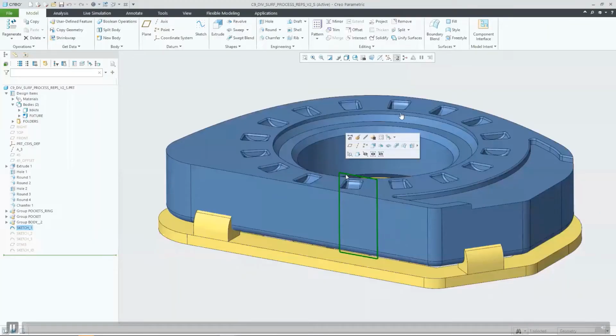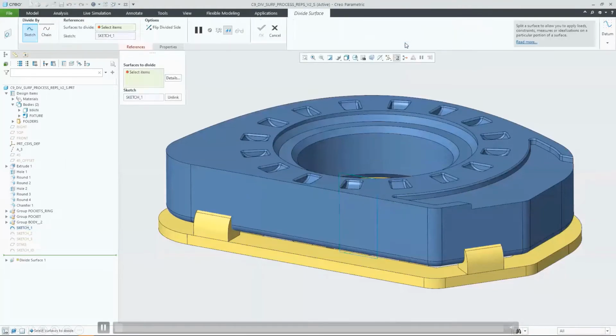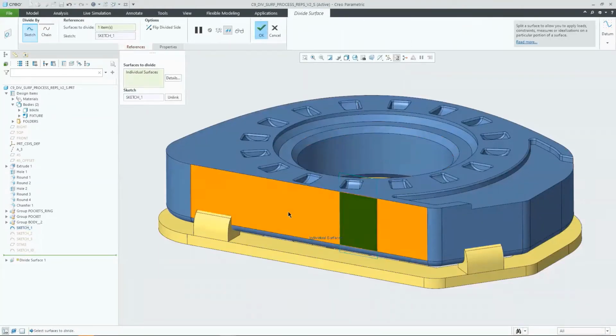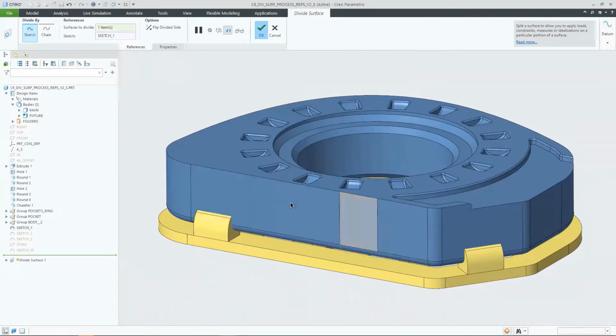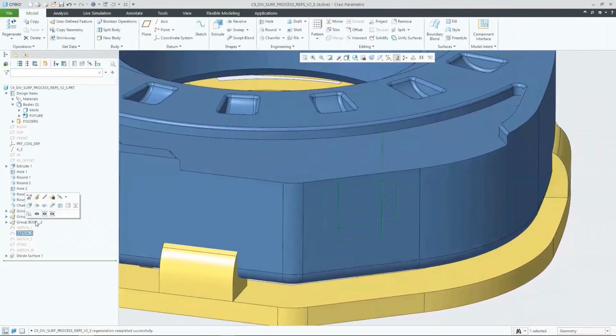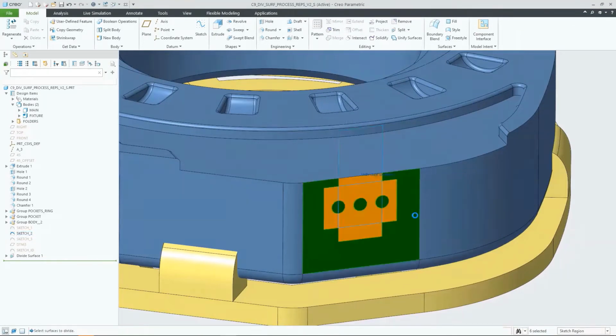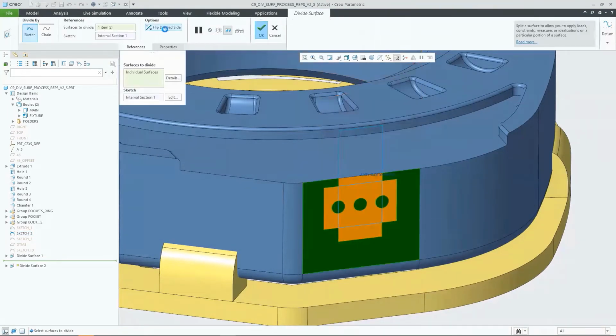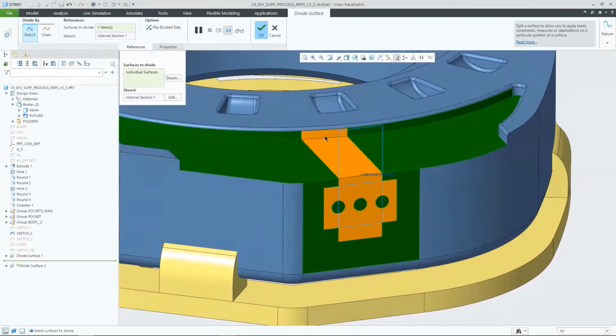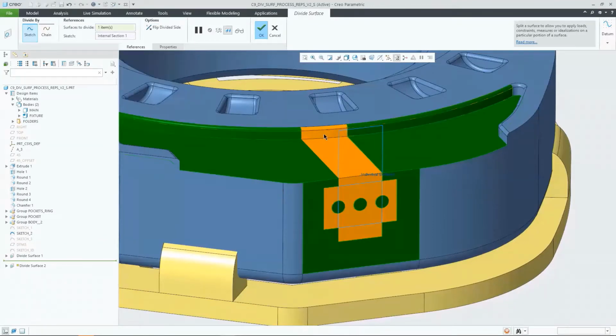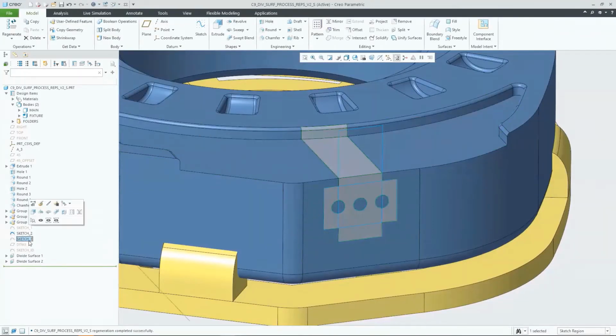Creo Parametric 9.0 introduces the new divide surface feature. You can now use the capabilities of the new divide surface feature in core modeling and throughout the broader Creo environment to split a surface area into a new adjacent touching surface that is based on the same surface definition as the original surface. This helps to better support a broad variety of use cases, for example in the areas of model-based definition, visualization, simulation, part modeling, data exchange, and more.